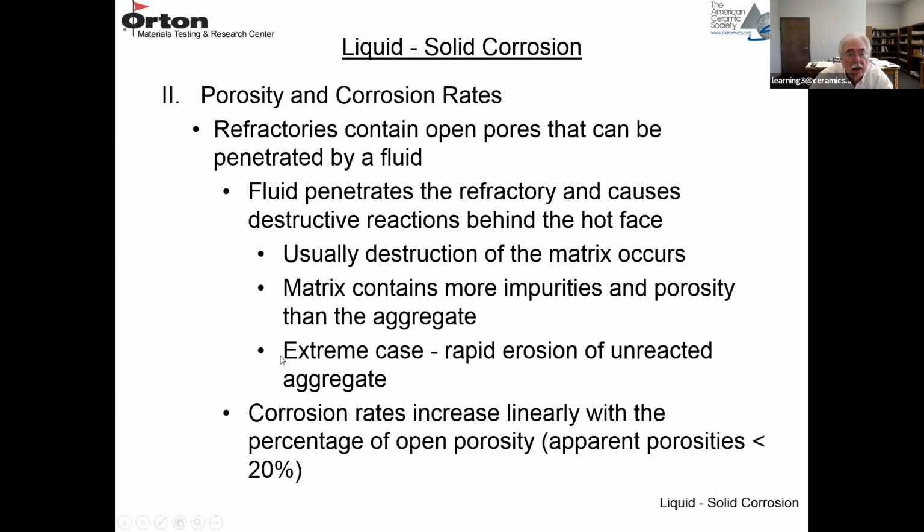And in the extreme case of corrosion, you dissolve the matrix and the unreacted aggregate is removed through the slag. The corrosion rates increase linearly with the percent of open porosity, and apparent porosities are, like I said, usually less than 20%.